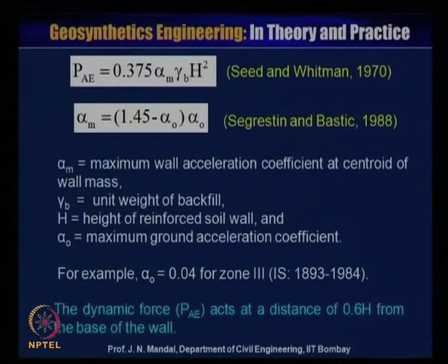Now, we have to calculate that dynamic force. PAE is equal to 0.375 alpha m gamma b into H square, which is given by Seed and Whitman 1970.